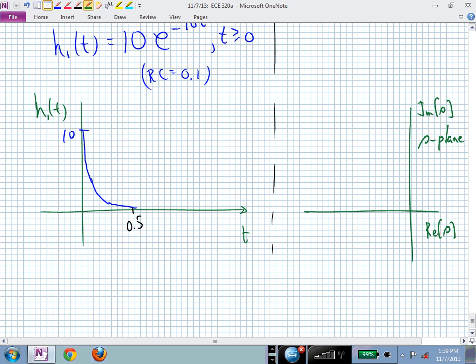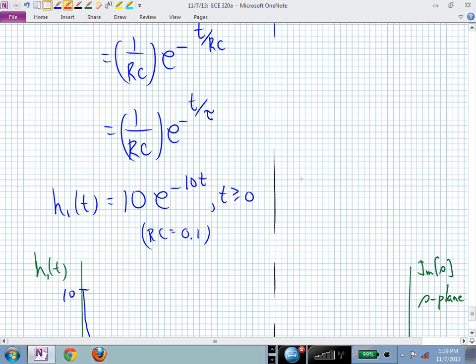I want the pole zero diagram because I want to think about the circus. The circus tent, this rubberized sheet on top of infinitely tall poles and thumbtacks. Thumbtacks being our finite zeros, and infinitely tall poles holding up this rubber sheet are our poles in the transfer function.